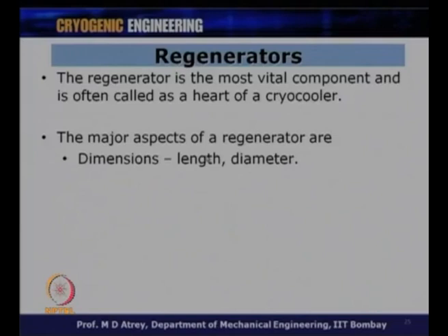Depending on what kind of compressor, what kilowatt compressor you are using, that means how much is the flow rate of the machine, in comparison to that, we will have to have a capacity of the regenerator, which is determined by the length and the diameter of the regenerator. Alright, so regenerator material will be housed in these dimensions. It will have its volume, and this regenerator matrix should be able to take the heat given by this gas during its travel through this regenerator, and therefore, the dimension of the regenerator you have to calculate very, very critically.